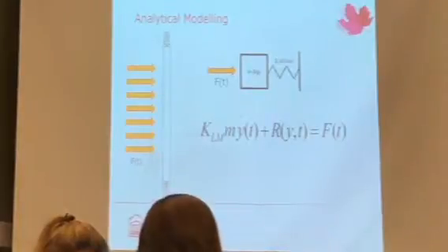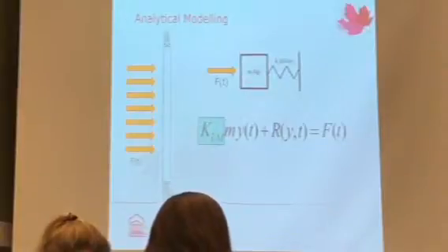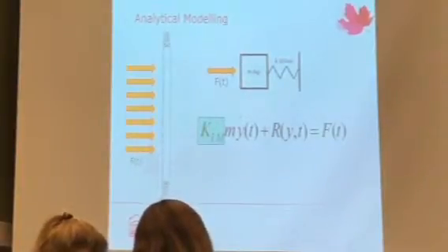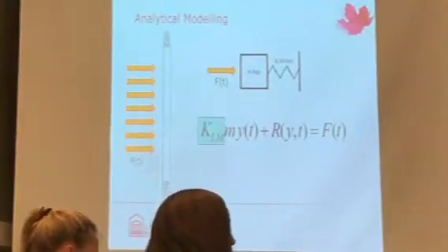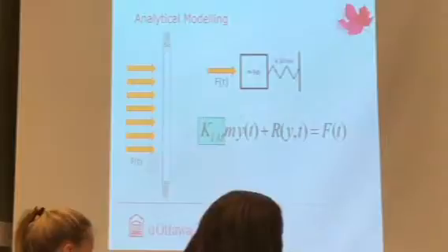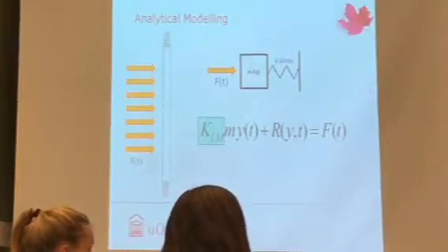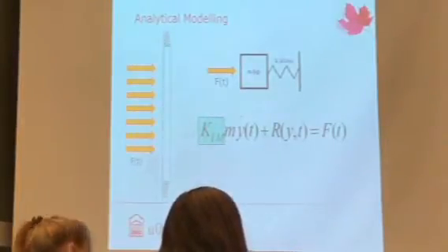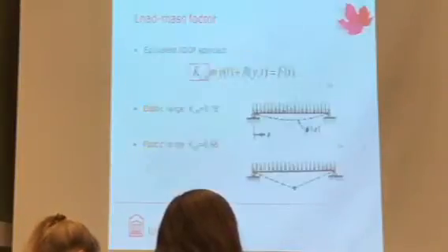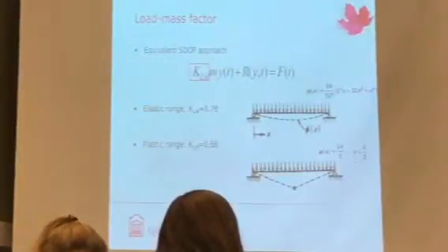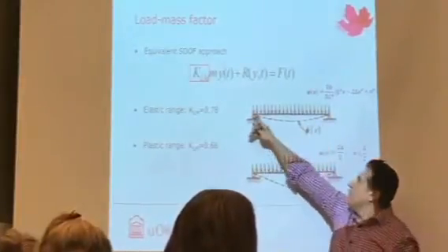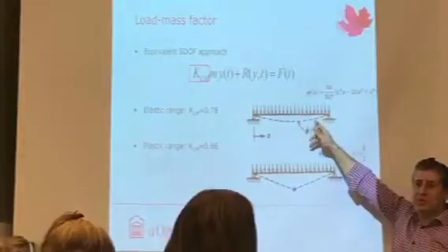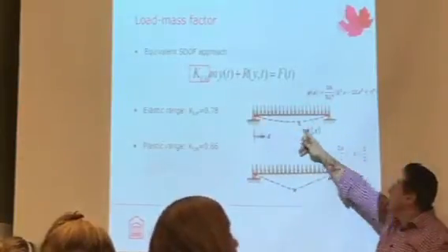First, the KL factor. I want to explain it because I don't know if you had it in this class or not. You either talk about a complete system, a multi-degree system, or a single degree of freedom system, right? This is telling you how to go from a complete, continuous system into a single degree of freedom system. You can simply do it by developing these factors. I'm giving you two cases. One case is where you have a simply supported, uniformly distributed load, where you get this sinusoidal shape.